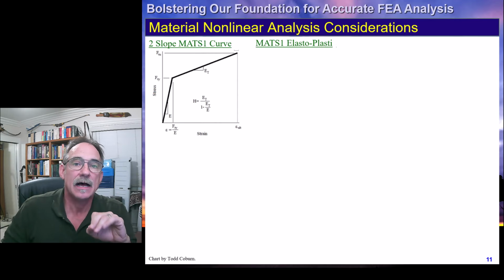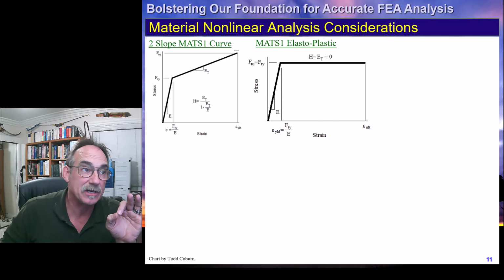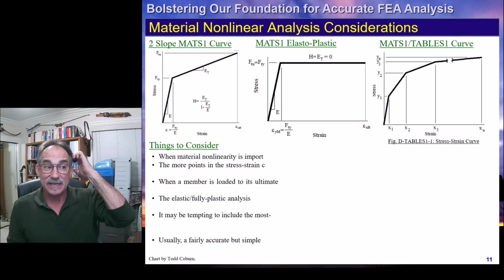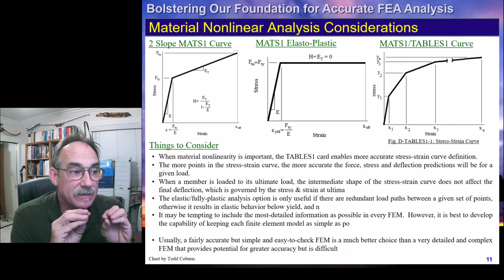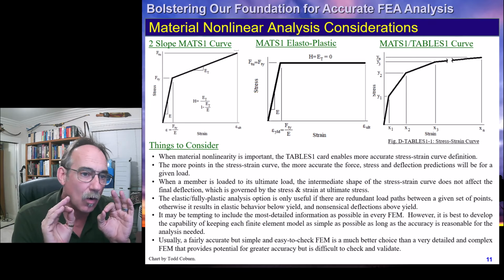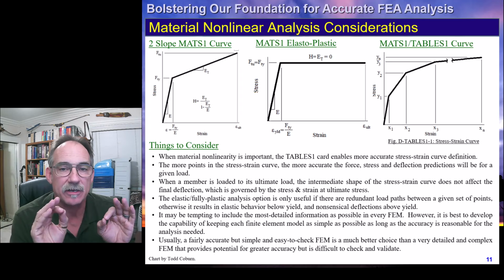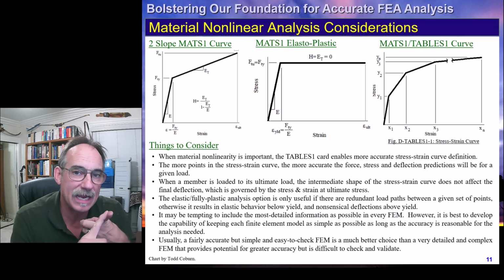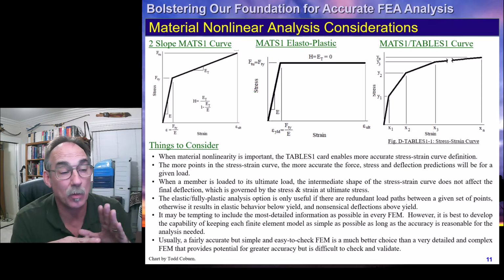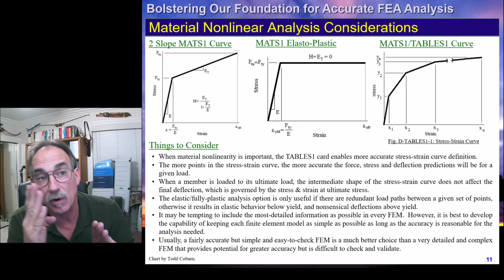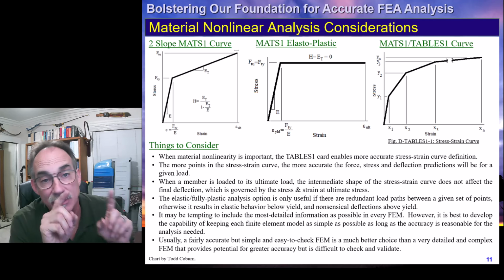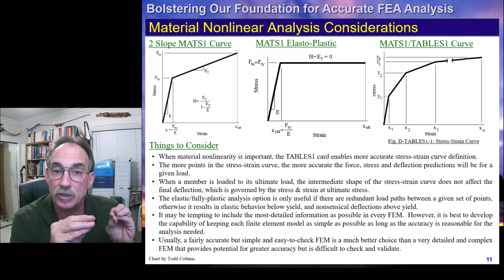If we're talking about nonlinear analysis, material nonlinearity, there's a few different ways to do this. Once again, these tools can be difficult to use correctly, and the only way to do this correctly is to first make sure you understand what NASTRAN can do, how it works, and what the limitations of each of these are, whether we're using a 2-point stress strain curve or a multi-point, or where we're trying to do elastoplastic analysis, and how to calculate those parameters that get fed in to do this correctly.